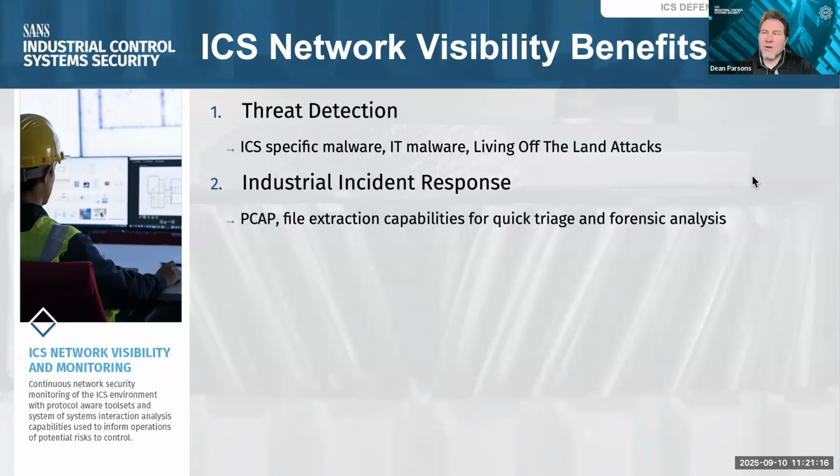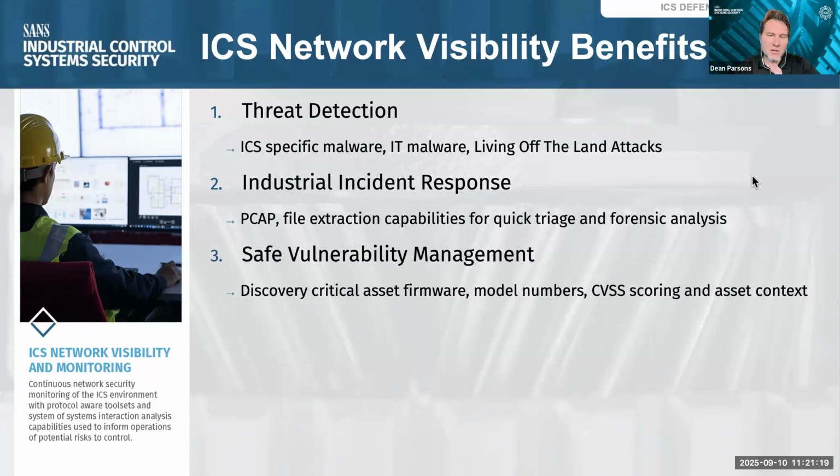Not only does it do that, it provides you safe vulnerability management, meaning when the communications are happening on the control environment, you're seeing the protocols and the devices that are communicating, not just the IP addresses, but how they're communicating, how often they're communicating, the devices themselves, the model numbers, the make, the firmware versions. All of those things are going to be seen passively and safely in the environment. There are other ways to achieve vulnerability management inside of a control system. I would wager that they're still more risky than this passive assessment view.